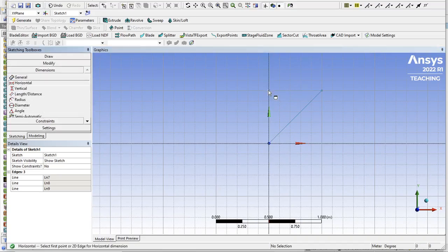We can dimension it if you like. I'm just showing one of those, so the dimension is 0.5. You can change its dimension if you need to modify this sketch. But essentially, this sketch is defining the path of the center line of different truss members.